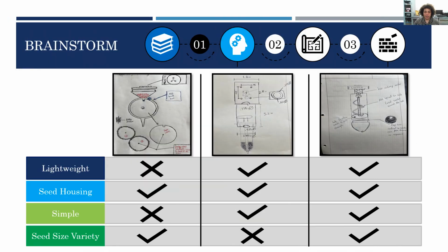To improve the seeding operation, concepts were generated with the main focus of housing and dispensing seeds directly from the end effector. This would eliminate the repetitive movements of retrieving seeds, which would decrease the movements performed and reduce operational time. Along with the two main factors, generated designs need to be lightweight and compact, allowing them to maintain a connection to the universal tool mount, or UTM, and be placed along the tool bay attached to the Y-axis gantry post-use. We also wanted the FarmBot to have the ability to dispense a variety of seeds, so two concepts were generated, one for small seeds, mainly basil, and another for larger seeds.